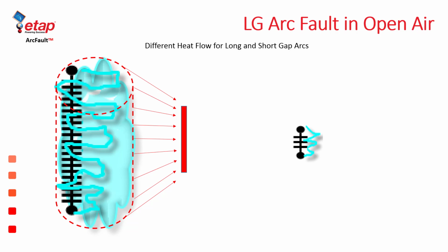Of course, this is opposite or counterintuitive to the classical models of the IEEE 1584 world, where the faults go up to 15 kV and have gaps in the range of fractions of an inch to 5 or 6 inches. In such short arcs, different models of heat expansion and heat flux could be used, which could be better represented using a spherical approach.